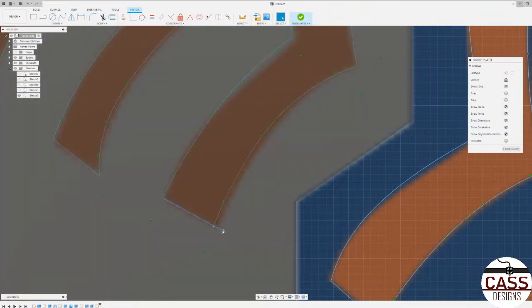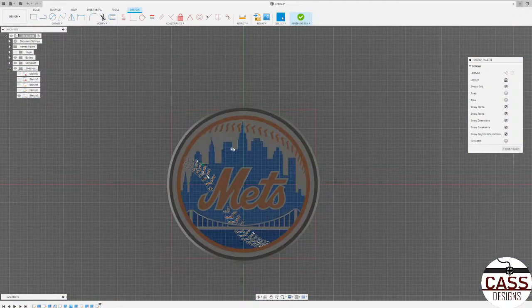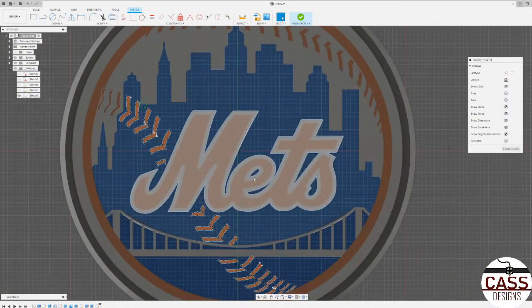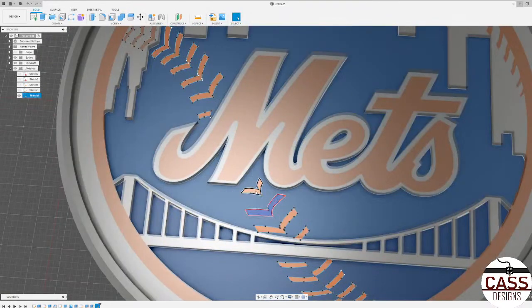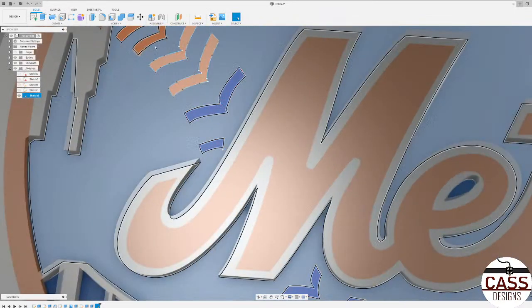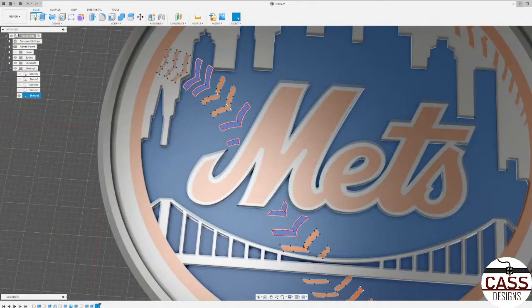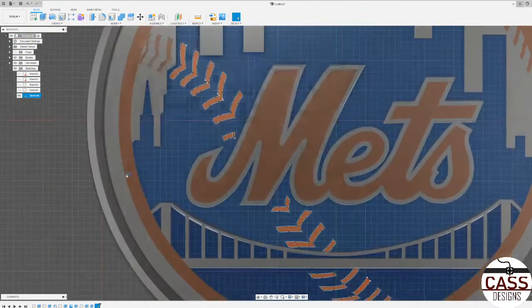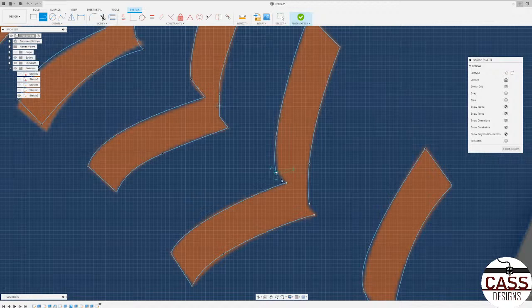Extend it a little bit on that one. Okay. So just to see if this works, we'll do the top half in a little bit. So I have the sketch finished. If I control click, which is similar to a lot of things on your computer, it highlights many closed loops. And as you can see, it's not selecting this one here, which means this loop is not closed. So let me go back and edit. I missed a couple lines. My apologies. So now it should be closed.